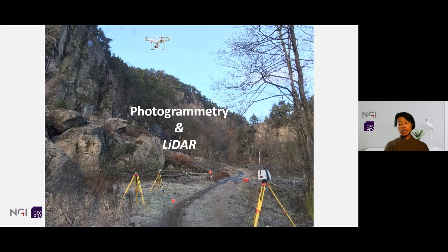There are 2 major techniques that are mainly used in obtaining 3D models of rock slopes in geosciences. One is photogrammetry and the other is LiDAR scanning. We can use either of these to get 3D models, depending on the project size and locations and the environment. We can also use both to supplement each other. For example, one can use a LiDAR model to georeference the photogrammetry model, which makes use of the high accuracy of the positioning from the LiDAR model, but also full color from the photogrammetry model.